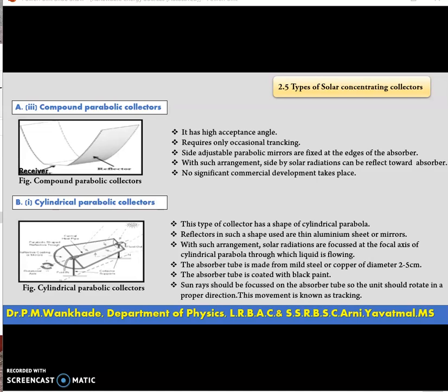Tracking we have already defined, that is, a technology for orienting a solar collector, reflector or photovoltaic panel toward the sun. As the sun moves across the sky, a tracking device makes sure that the solar collector automatically follows and maintains the optimum angle to receive most of the solar radiation. That's why we require tracking. Some solar collectors hugely benefit from tracking while some others do not. So the tracking system can be added with additional cost and certain trade-offs in system design only when it pays off.